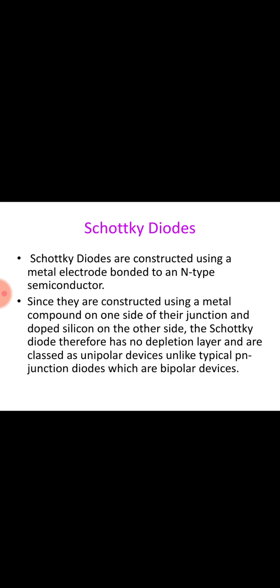The classical PN junction diode commonly used at low frequencies has a relatively large junction capacitance that makes it unsuitable for high frequency applications. The Schottky barrier diode, however, relies on a semiconductor-metal junction that results in a much lower junction capacitance, allowing operation at high frequencies. Commercially available microwave Schottky diodes generally use N-type gallium arsenide material, while lower frequency versions may use N-type silicon.